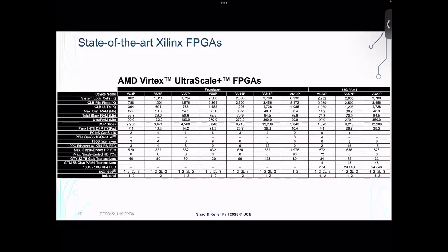Okay, so if you are an FPGA nerd and you go looking in the data sheets, you'll see giant tables like these that talk about what's inside FPGAs. These Virtex UltraScale parts are the biggest ones you can get your hands on these days. The columns show different variants, different models of the FPGA, and the rows show the different components and how capable each FPGA is.